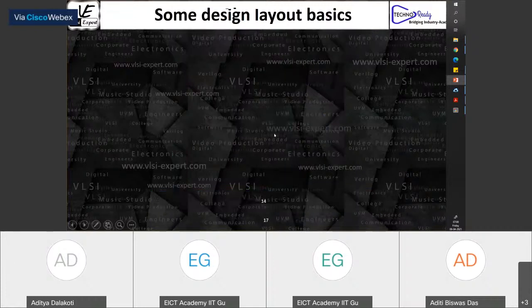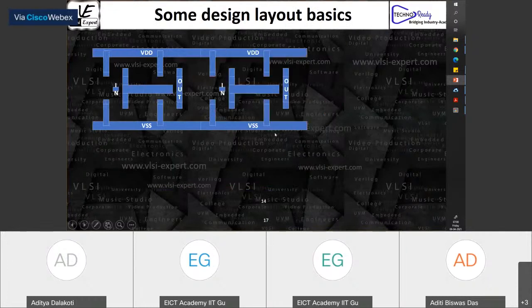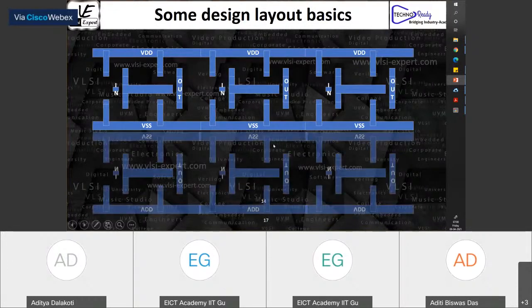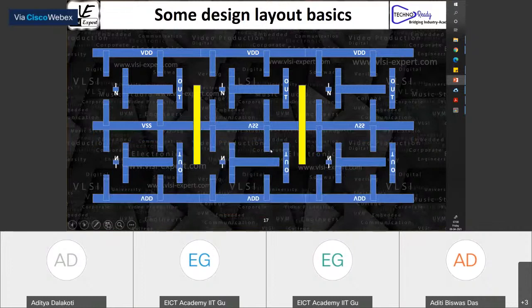Okay. Now, with respect to the design, your standard cells are connected like this, then flipped over. Then there are different vertical and horizontal routing metal layers available to you. Now, the question for the router is basically, are there enough tracks for you to be able to connect everything? That is the question you have to answer. So this is your routing over here, your routing over here. The question is, is this enough for you to route your whole SoC?